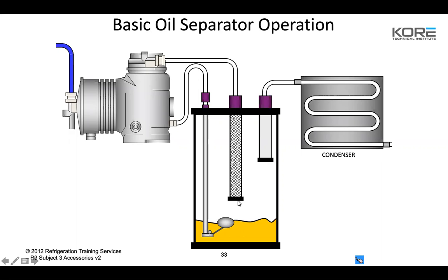So you may not think you have oil when you drop this, because it just keeps going downstream. When that oil flow gets pinned by this screen, what you want to do, anytime you're dealing with an oil separator, is drop that plate, and physically reach up inside there and try to grab that screen and move it with your hand. If it moves, you've got a problem. That thing should be welded in and not moving. It's stumped some of my best people. So just understand that when you're dealing with oil separators, if you have any questions on that, give us a call.